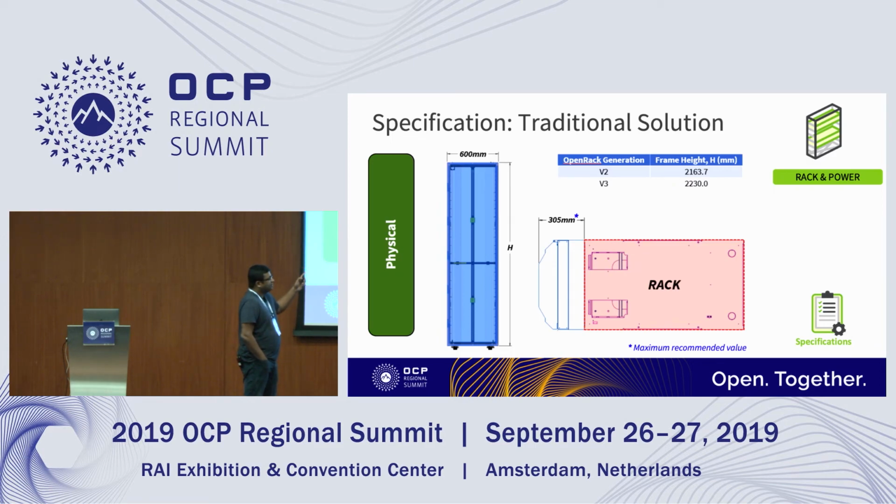And with regards to the footprint, the only components that are allowed to violate this requirement are the interfaces that you make, whether that's the coolant with regards to facility liquid coming in, or your electrical and communication interfaces. Also, you could have leveling feet for either load bearing or alignment requirements. That's fine as well. With regards to the depth, our recommendation is you keep this maximum value within 1 foot. We had one of the community members coming to us and saying, hey, our door heat exchanger is slightly more than 305 millimeters.